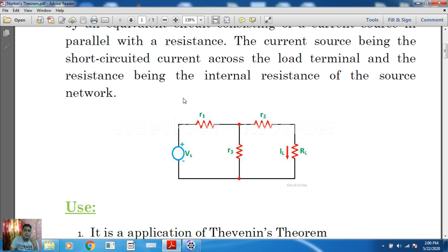In the last step, initially we found the equivalent voltage, which is now our voltage source. After that we found the equivalent resistance, which is now our series resistance, and the load resistance we had disconnected from the circuit is connected in series. Now we find the simple series current, which gives us the load current. So that was Thevenin's in short.